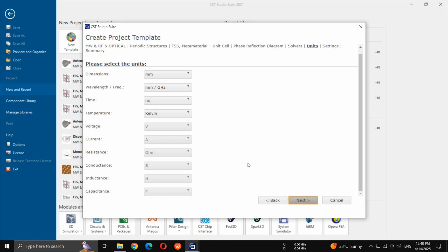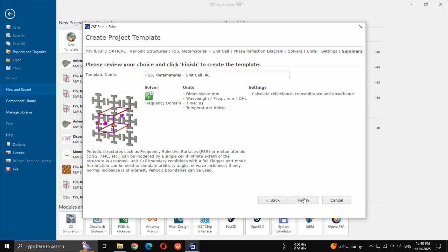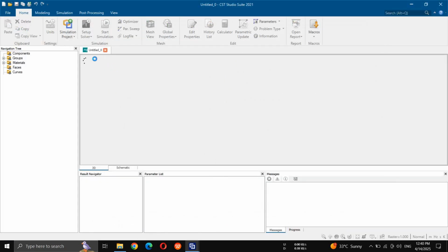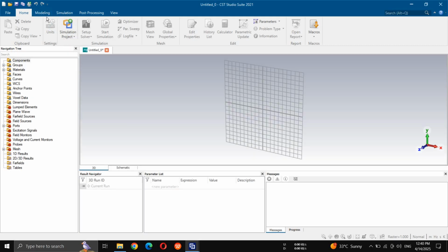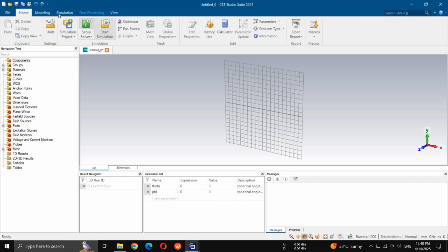So if I have 0 degree, the other one should have around minus 180 or plus 180. So first of all, I'm going to do design one, and then I will just change the parameters, and then you will see there will be difference in the phase and amplitude, which you can further use for designing your arrays. So let's begin.